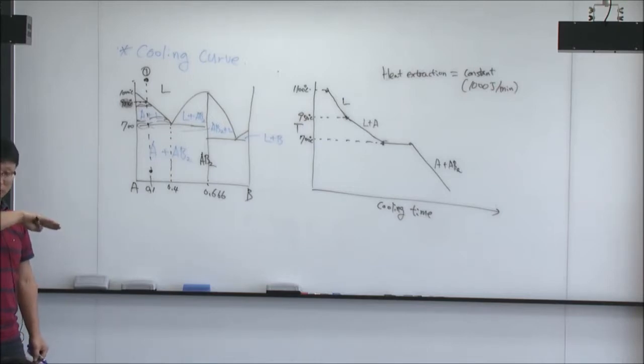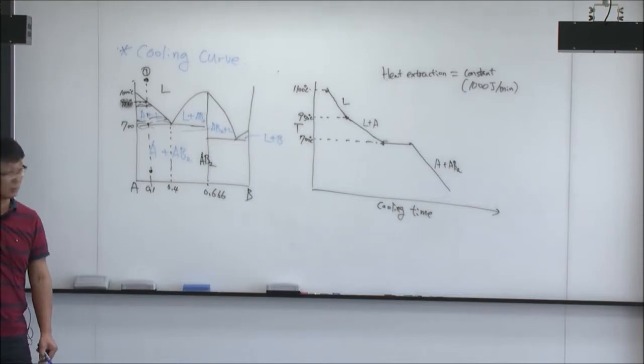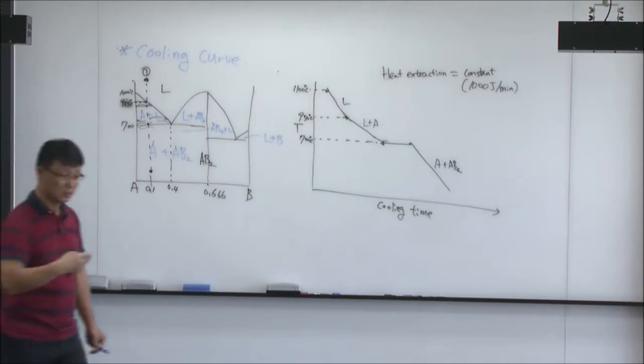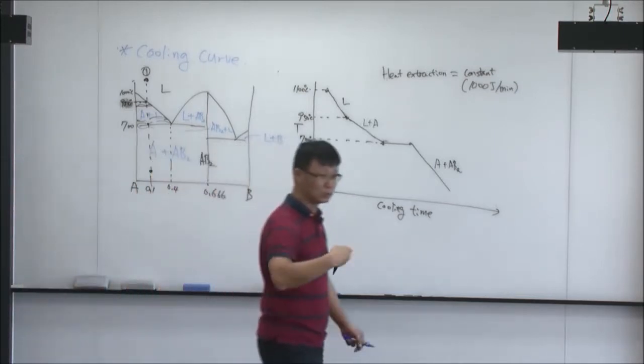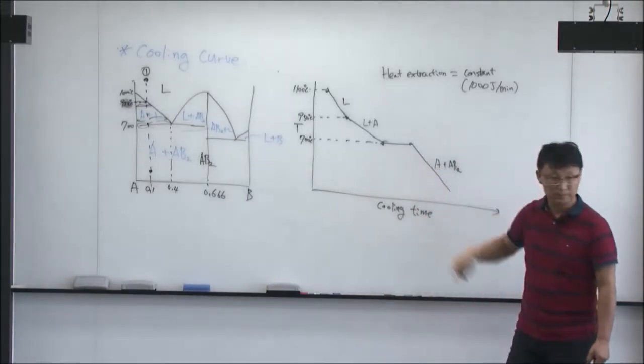If you increase the temperature of water until 100 degrees Celsius, it takes time to boil it completely at 100 degrees Celsius, and then the gas temperature goes up again. Because there's a complete change of a certain amount of solid or liquid into the other phase, it's not continuously changing, it's a sudden jump of the amount. So it takes time to complete that phase transformation at exactly the same temperature. That's why we need time here.